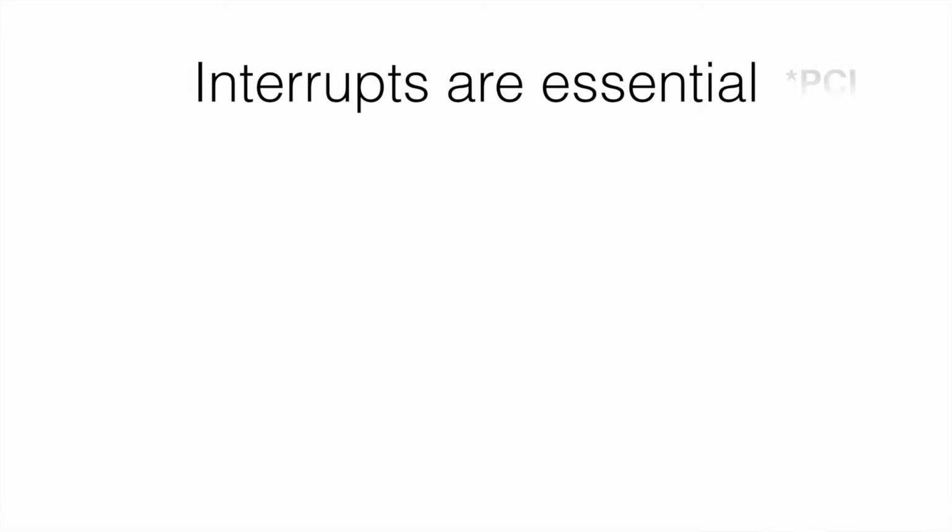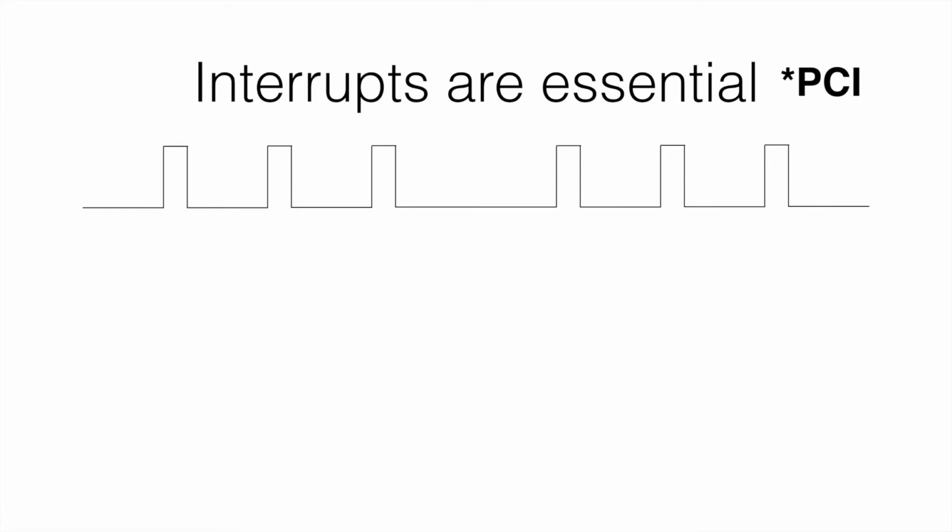Now, to calculate the channels, we will need to use interrupts. In particular, we will use a pin change interrupt. Again, I have the waveform of the PPM signal, and if I connect this waveform to an interrupt pin, I will have interrupts occurring at all of these positions. Due to the nature of the signal, we only need interrupts at either the rising or the falling position of the signal. In this example, I will use the rising pulses.